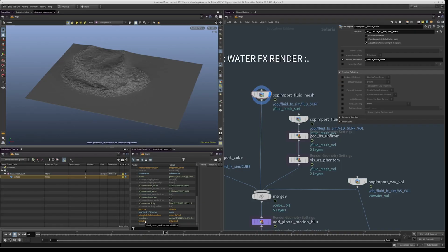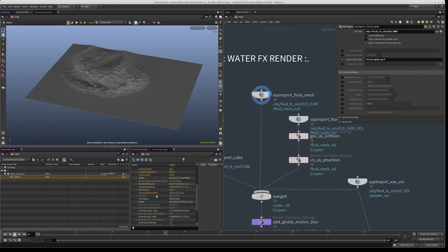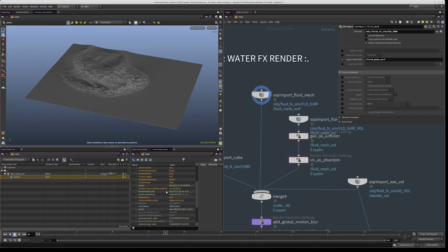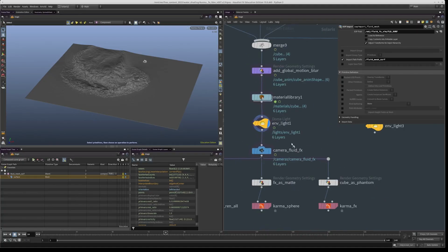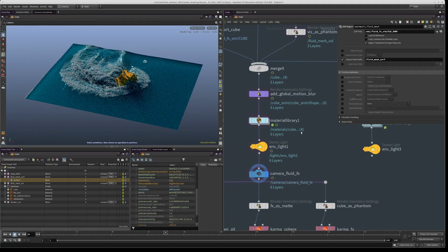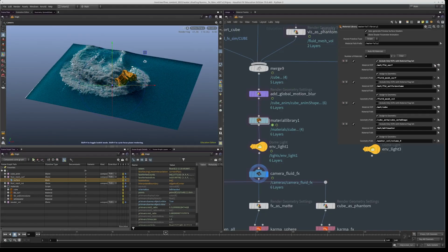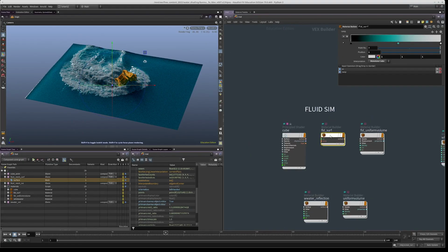It's called velocities. There's also a base color. We don't have it here, but if you need to access Cd with an uppercase C and lowercase d, which is the default workflow, it's not called that anymore. It's called base color, and that gets automatically renamed. So if you have shaders that rely on this, that needs to change to accommodate for that. Very, very important.